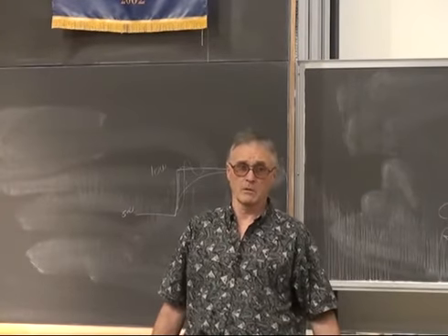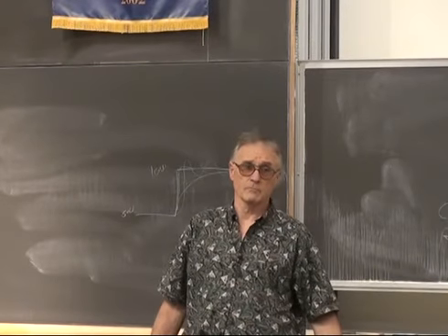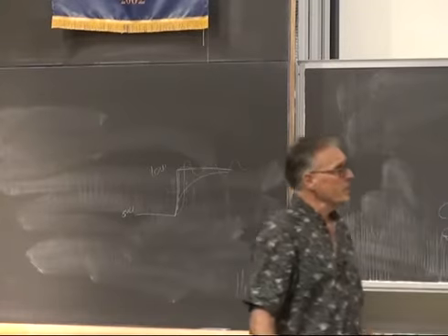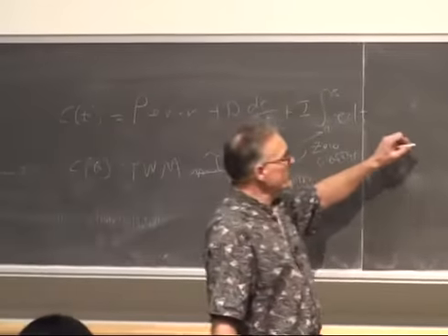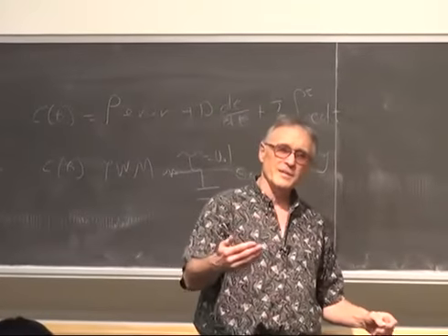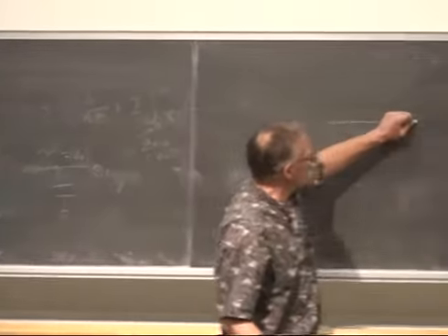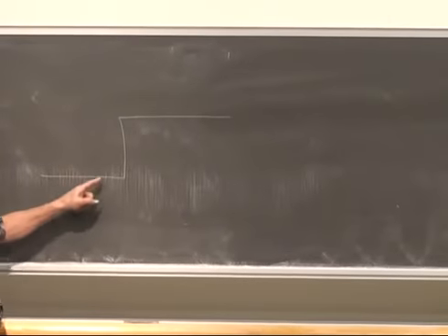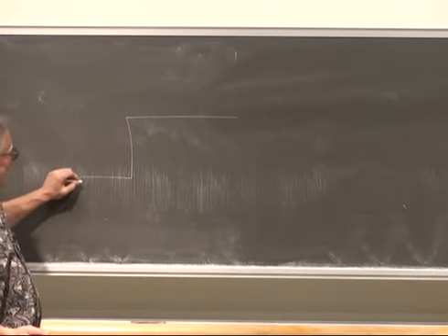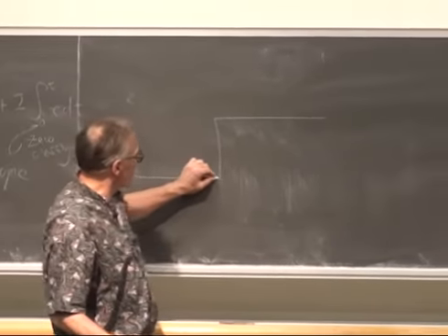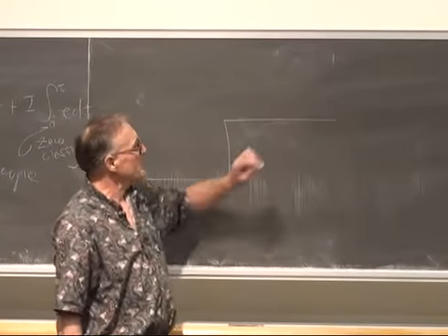Remember when we first talked about that, you talked about the zero crossing and how you don't want to reset something to zero? Yeah, I wouldn't reset the integral term to 0 on a zero crossing. Remember that you can't actually control the slowing down of the motor. So let's say you've stepped and this is the desired speed. Now the motor ramps up, it comes up to nearly a steady state.